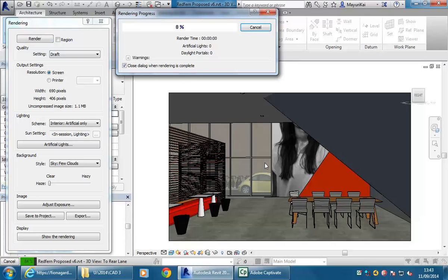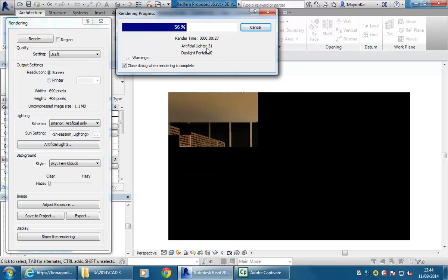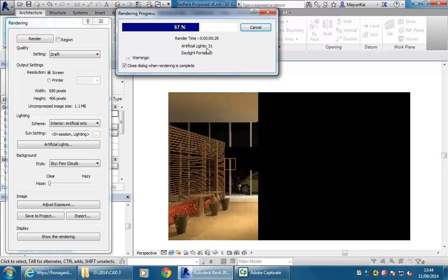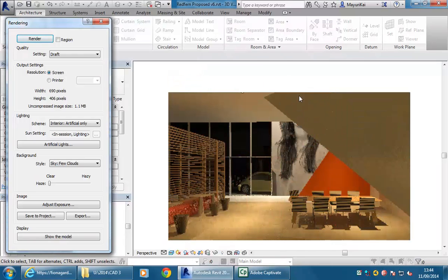So you see, I've only really worked with about five or 10 lights here up to this point, and I've seen a lot of people who add a lot of lights in and only after that start doing some rendering, and sometimes have by that stage about 100 lights when it will really slow down. I do have other lights in other spaces here, and so I've got 30 lights, which is still, I think, a bit too many, but at least I haven't got a ridiculous amount. So there you can see some nice light coming down from the level above. I'd be happy with that.